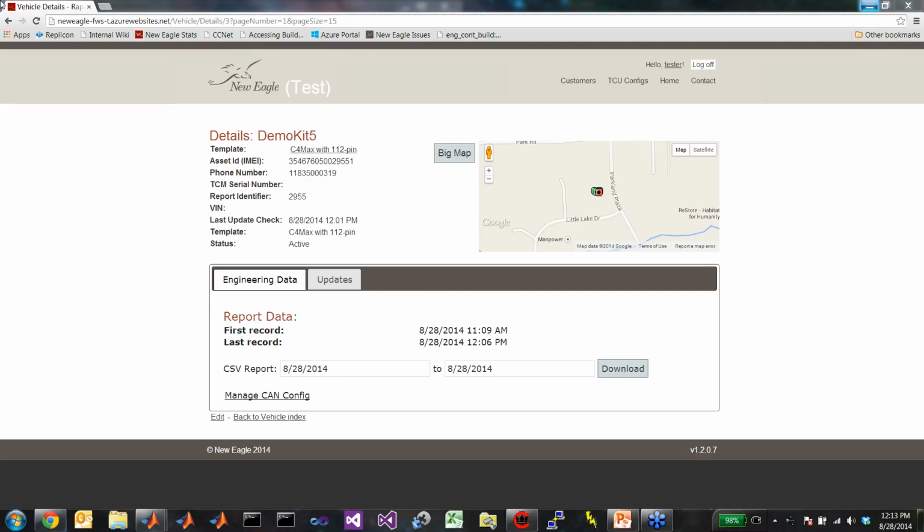If we needed something more sophisticated, actually switching between multiple configurations based on a state, that would be a sort of custom application that we would need to work on for that specific application. And another thing to point out is this is configured via a DBC file. So what you put in your DBC file is what gets collected.